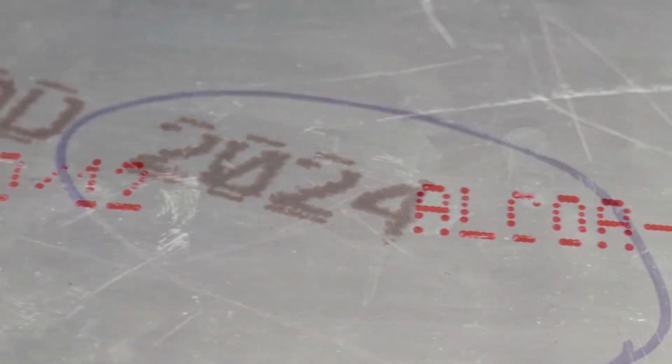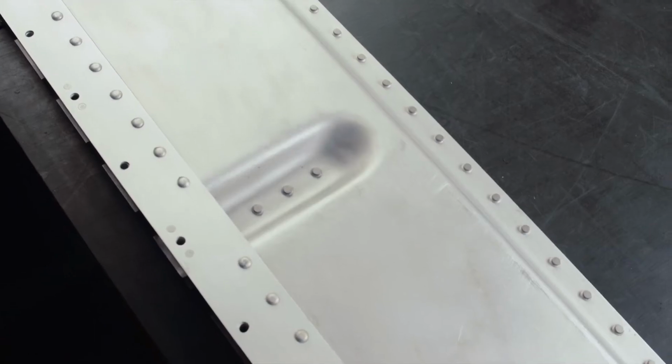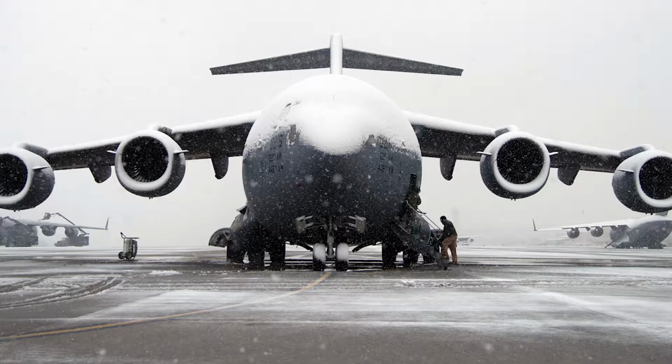Pure aluminum is very corrosion resistant, but in order to improve strength, magnesium and copper are added to form aluminum alloys. While this strengthens the material, the aluminum can act as an anode, and the alloy metals can act as cathodes. All that is needed is an electrolyte to complete a corrosion cell and initiate corrosion.